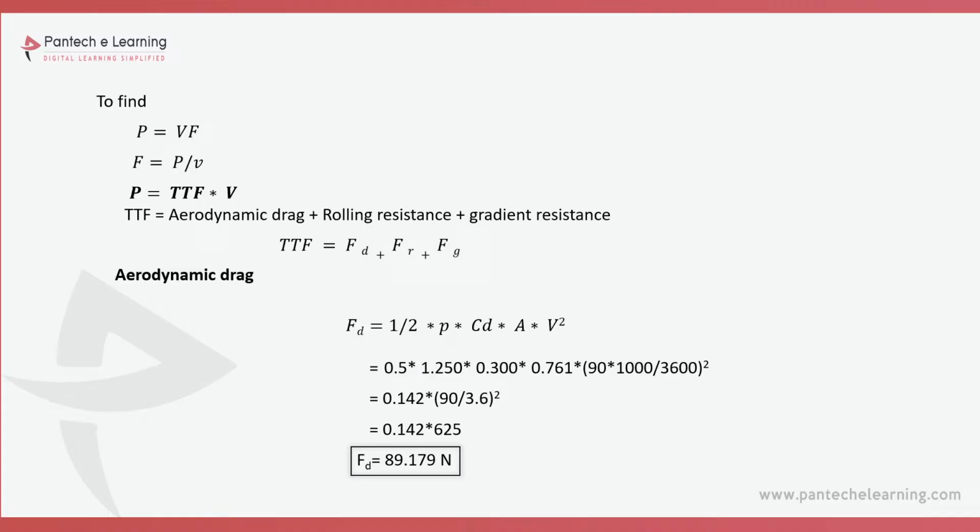Here the force is considered as the total tractive force, so power equals TTF into V. What does total tractive force mean? It is the sum of these forces: aerodynamic drag, rolling resistance, and gradient resistance. So we can see here.